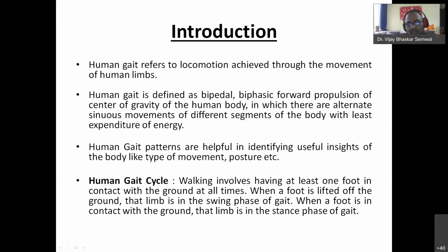The entire universe is non-linear. Whatever you perceive through your eyes or from the environment is non-linear in nature. You have to do piecewise linear modeling. As in the morning I was showing the hybrid automata model, I divided human gait into subphases, initially swing phase and stance phase. Then further division into pre-swing, mid-swing, initial swing, mid-stance, terminal stance, and like this I divided into 7 discrete subphases. These 7 discrete subphases are 7 linear classifications of a non-linear system.